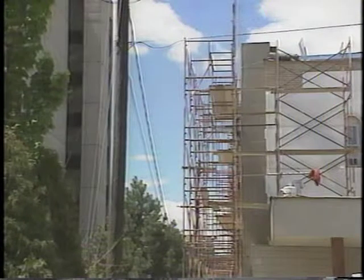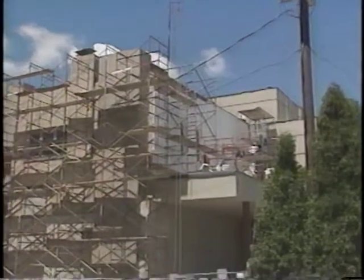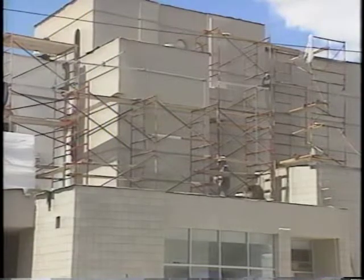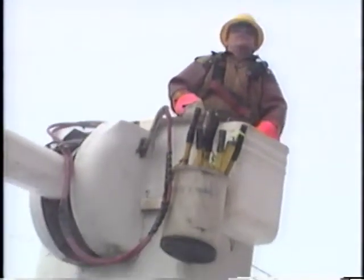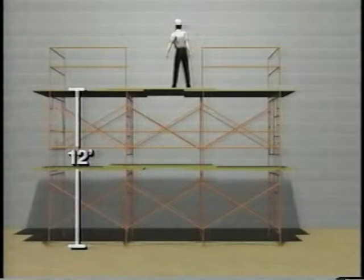A minimum safe approach distance of 10 feet must be maintained at all times between the scaffold and energized power lines. The 10-foot safe approach distance also includes any conductive materials used on the scaffold. If work must be performed within the safe approach distance, contact the proper utility company first to either de-energize or move the lines.